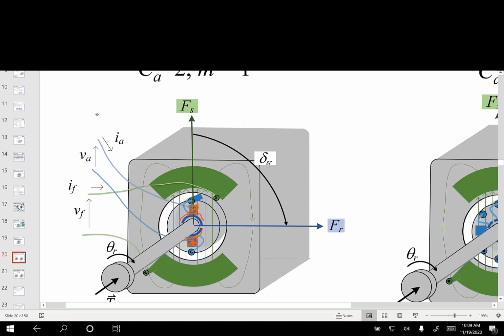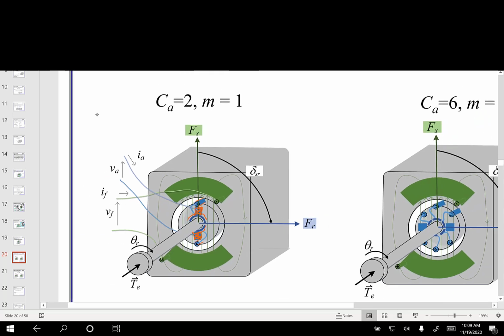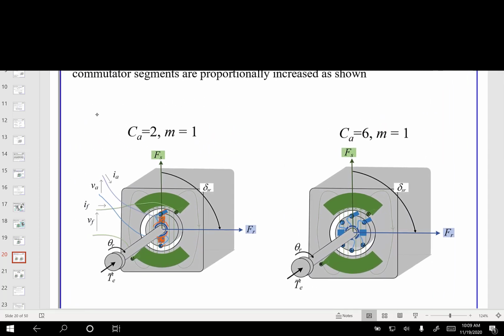If we were together, I would be sending you around one of these, and you could take it apart and look at it. As the rotor shaft moves, it flips rotational direction at these gaps. But I'm only showing one segment, and really each segment aligns with one coil, which is in one slot. From what we learned, that's a poor utilization. You really would want to distribute out the energy.